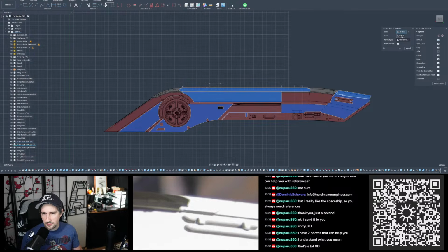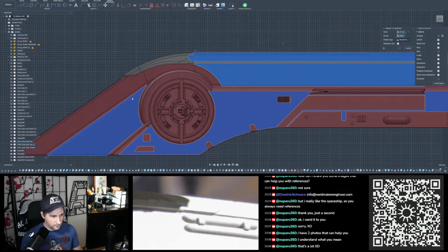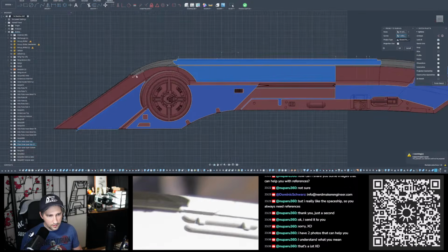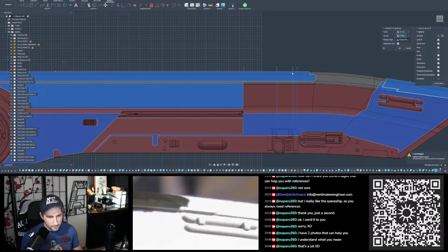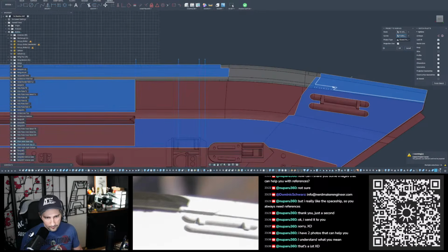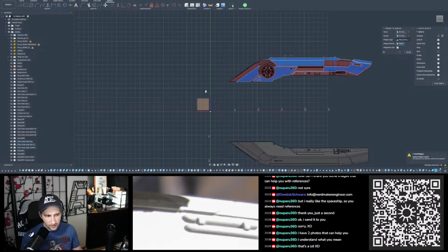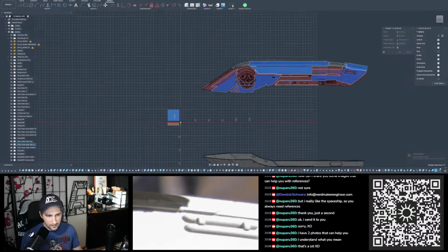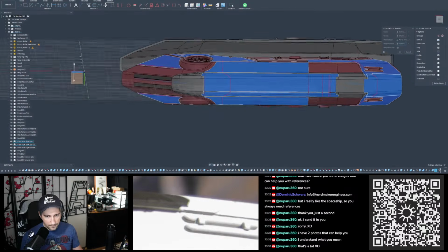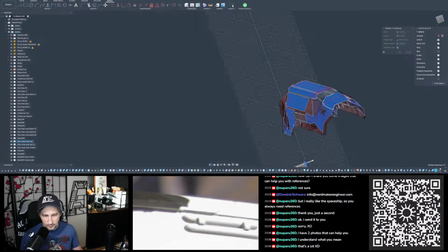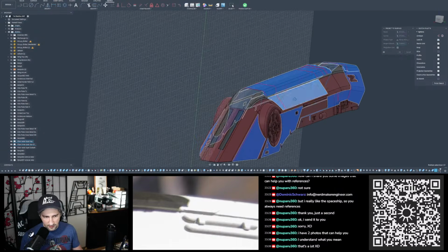So now we select all the lines that we want to be projected. And we want them projected along this plane. So now you can see the red lines. I projected them onto the surfaces that I selected.